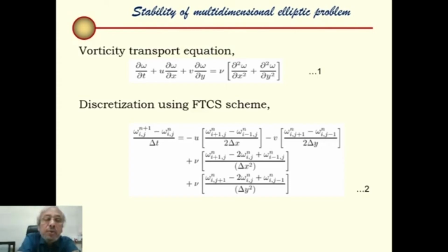I am sure all of you know what the vorticity transport equation is. If the x momentum equation is differentiated with respect to y, and the y momentum equation is differentiated with respect to x, and then the former is subtracted from the latter, we get the vorticity transport equation.